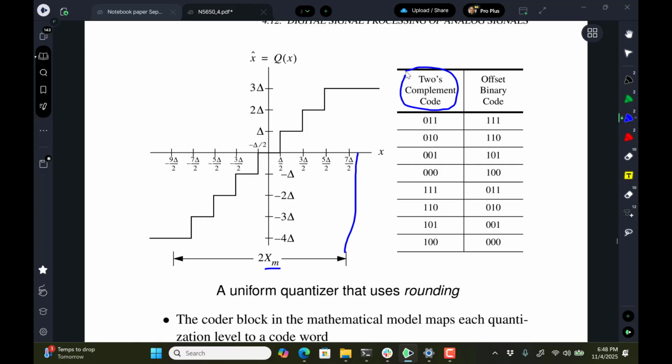There's offset binary, but 2's complement is what's used on our computers. And if there's bipolar things in converters, it's generally a 2's complement form. And I made that assumption in problem 3. So now we're getting close to touching problem 3 from the project, where we have the assumption of a 32-bit word, and we're using signed arithmetic.